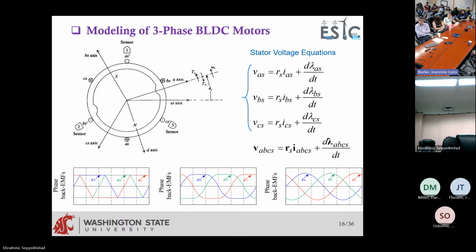Purely sinusoidal currents. So what happens is that if you have a back EMF like this, and you have three voltages connected to the stator winding, let's say pure sinusoidal, then impedance RL, then plus these back EMFs. These back EMFs have harmonics in this case, so they will also cause ripples. So it all depends. It's one voltage minus the other one divided by the impedance. So you can have harmonics here, but they cancel when they get subtracted. Thank you so much for clearing that up for me.